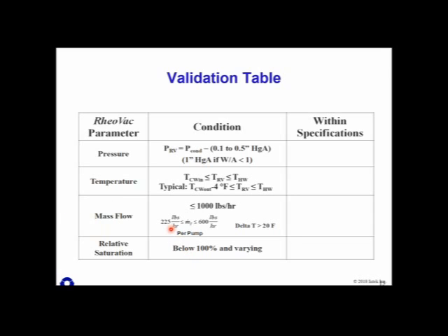Anytime you suspect a problem with your condenser and it's air and leakage related, or the re-evac seems to indicate it, go through these steps. Validate the data first. Number one, the re-evac pressure should be slightly less than the condenser pressure. It's downstream of the condenser. It should be slightly less, about 1/10 to 5/10 of an inch.